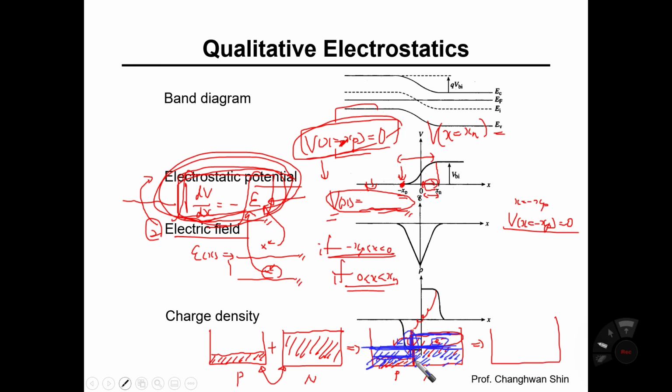In other words, originally there is a potential barrier height between P and N. Okay, so that value, we have no idea how much it is, but across the PN diode there is a built-in potential. I said built-in. Built-in means spontaneously, in nature, not from external force. Okay, so spontaneously P and N-type materials have formed the built-in potential.